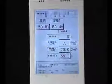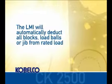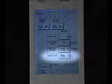The actual load is the present load on the load block or ball within a 2% error factor. The rated load is the max amount of total weight the crane can pick up at its present configuration. As an aid to the operator, the LMI will deduct unused blocks or jib from the rated load. The radius indicates the distance from the center rotation of the crane out to the load block.